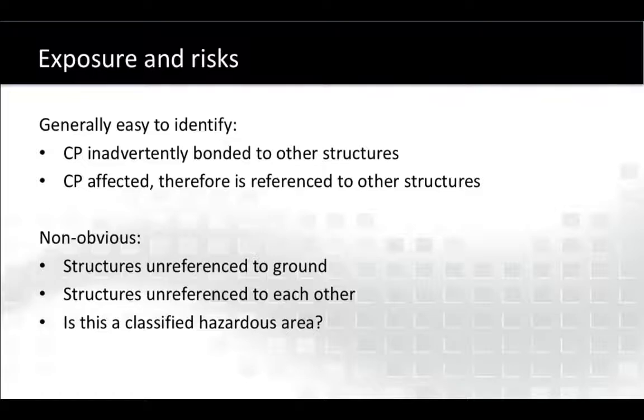What might be less obvious is when the opposite occurs. When CP is fine, but what they might not be focusing on is that those structures remain unreferenced to ground, or they are unreferenced to other nearby structures, and then those points can support voltage. Finally, another less obvious issue would be if any of this is in a classified hazardous area, and then certain products and methods and practices must be employed.